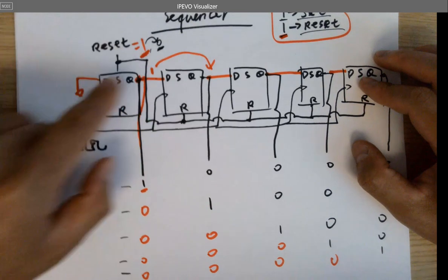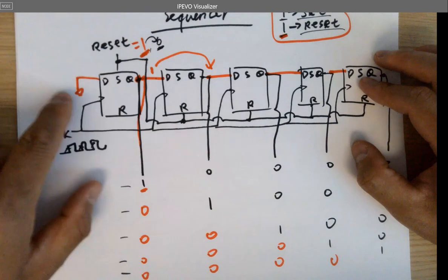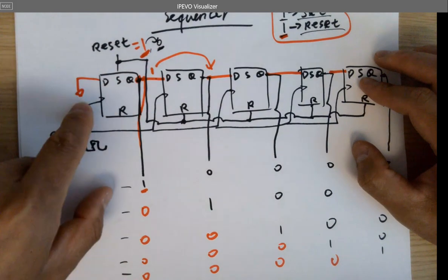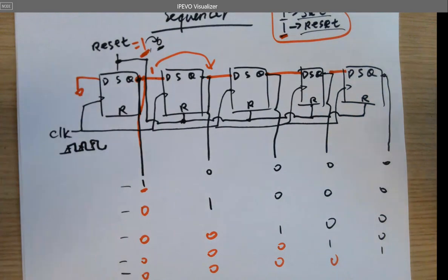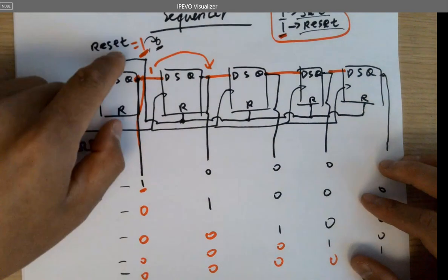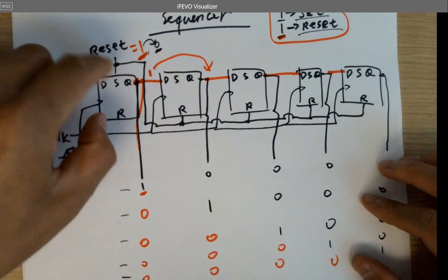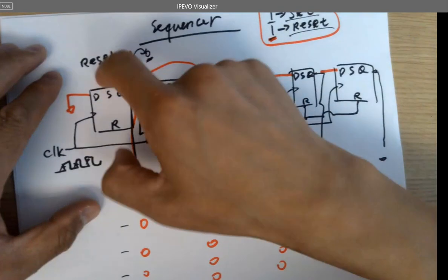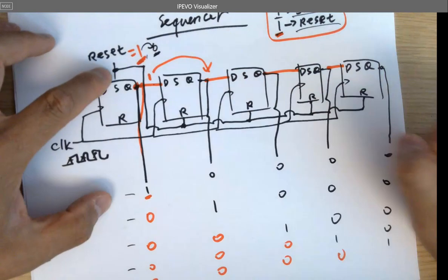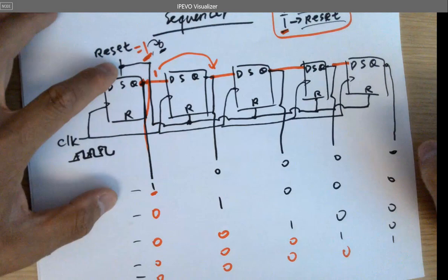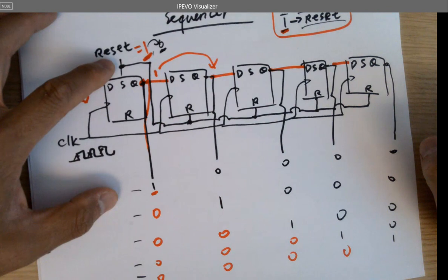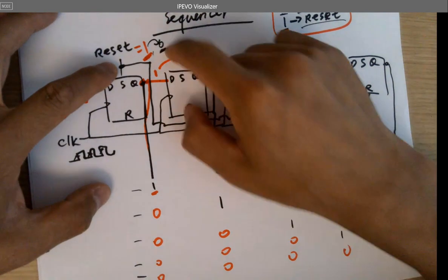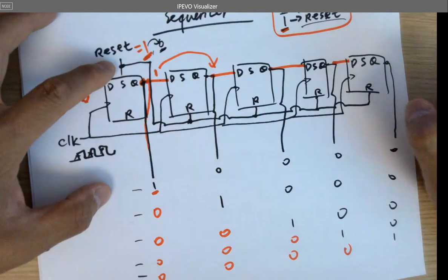Okay? Even though when you release it, it might send D to Q at some point at the rising edge, but it doesn't matter. Whenever I need it to be 1, I set it or reset it. It doesn't matter because I'm connecting this wire to all the reset of the following ones, but set to this one. So if I put a 1 here, it's going to set it. Okay? 0 to what? 0 is going to release it. It's going to be a D flip-flop.